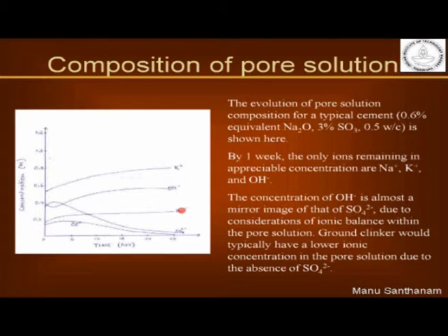So now you have your sodium and potassium which are present in very high concentrations inside cement paste after about 7 days. Now what happens to the negative ions? Since there is a positive ionic concentration, potassium and sodium, you also need to have a negative ionic concentration maintained. So in this case the negative concentration is maintained by hydroxyl, OH minus. Where is OH minus coming from? It is coming from your calcium hydroxide, Ca(OH)2. So you have your calcium also coming here. See here, this is your calcium. The concentration of calcium, which is very high in the beginning, is not very high in the end, but it is there to some extent because it needs to provide your hydroxyl ion concentration in the system.